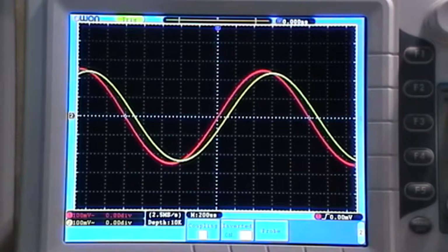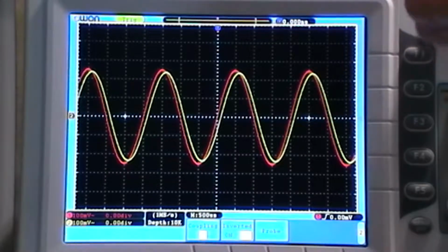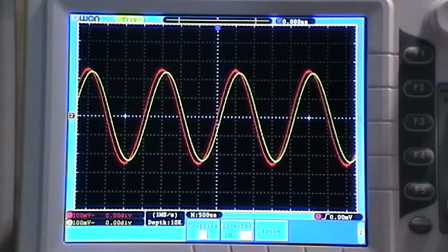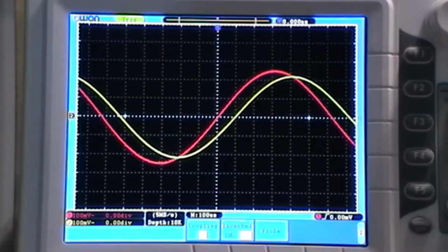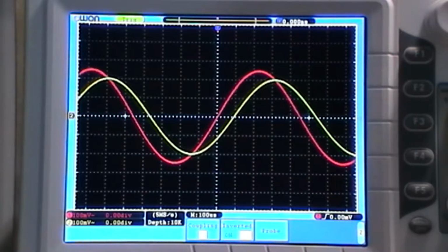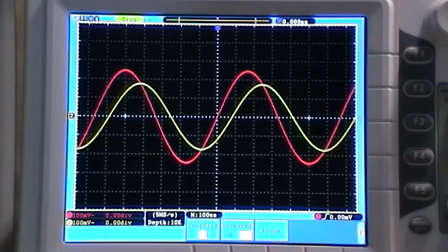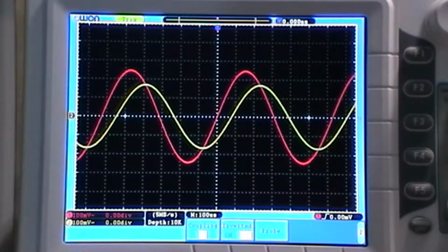and you can see that at the moment it's slightly clipped, but then in this type of circuit there's always going to be a slight bit of loss unless you're way off from the cutoff point. So what I'm going to do is just stretch that out a bit. I'm going to turn this frequency up until we start to see it come down, and we need it to be really at, according to this, 1.59 kilohertz or 1.6. So that's at 1.6 kilohertz.